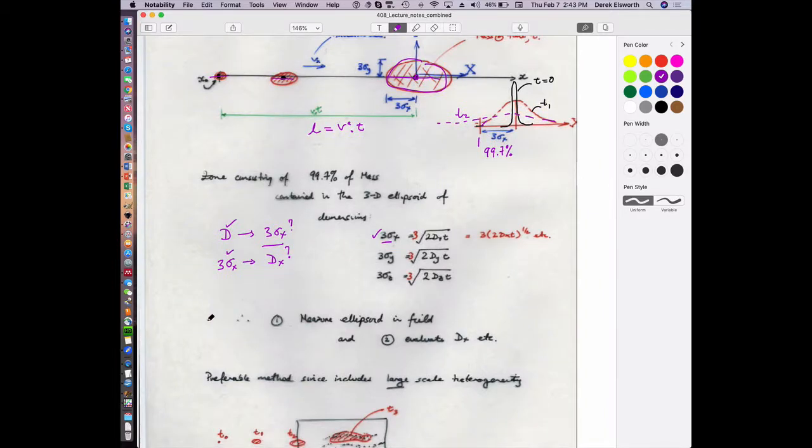The interesting thing which we'll find out is that this dispersion value, here d sub x maybe, for looking at dispersion in the longitudinal direction, so we've called this d sub l, and we said that in terms of processes, it's equivalent to the diffusion that's in our system plus advective mixing or mechanical mixing times velocity.